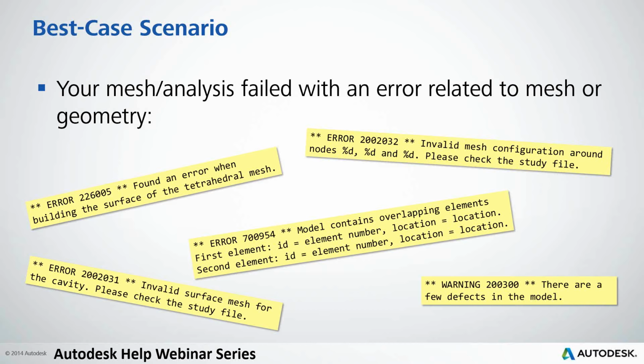Again, error messages would pop up with that analysis failed. Warning messages might just show up here and there. They don't necessarily stop the analysis from running, but they will bring it to your attention in that log file. Now, sometimes you might see a couple of warning messages and an error message, so use those to help take a look at what could be wrong in the analysis failure.